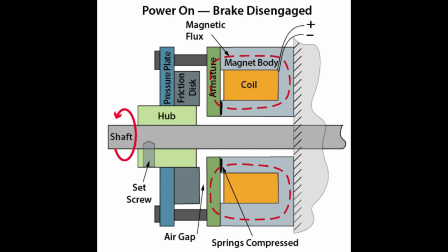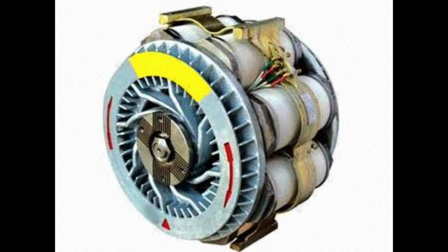To ensure the proper working of the electromagnetic brakes, a magnetic flux is passed in a perpendicular direction with respect to the rotating direction of the wheel. There is a rapid current flowing which is observed in the opposite direction to the rotation of the wheel. This develops an opposing force to the rotation of the wheel, which slows the wheel down.